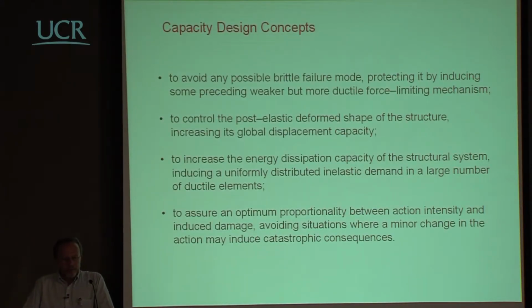From the point of view of capacity design concepts, the idea is that we want, again, to avoid any nonlinear response which is not in the isolation system. We want to control the post-elastic deformed shape of the structure, in general increasing its global displacement capacity, and we want to increase the energy dissipation capacity to reduce the displacement demand.